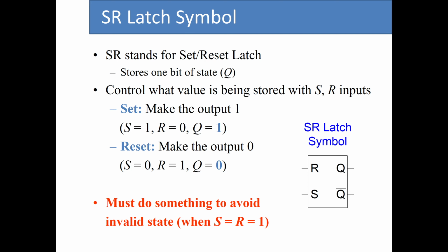So let's just recap what I talked about the SR-Latch. So SR again stands for set reset latch, and it is used to store 1 bit of state or value for Q. So we have control over the value that we want to store in the SR-Latch, and the way that we do it is by choosing the values for S and R. So if we want to store a value of 1, we put S to be 1 and we put R to be 0.